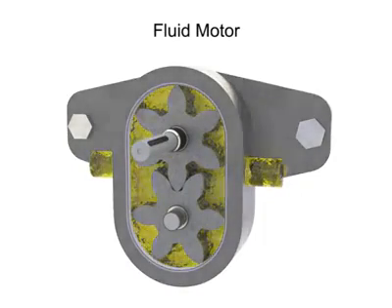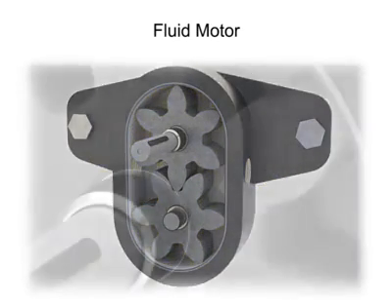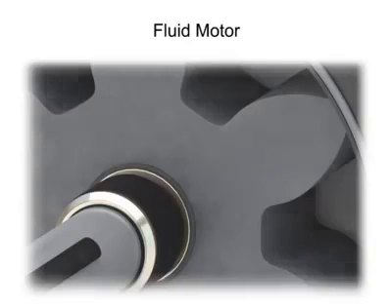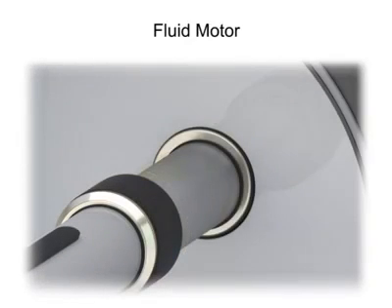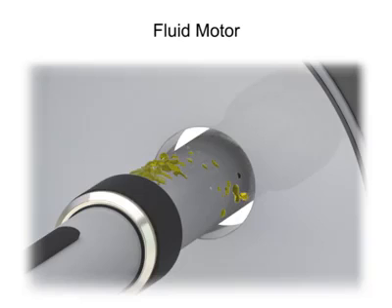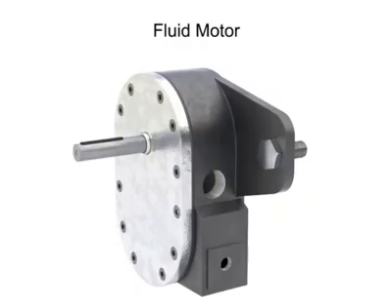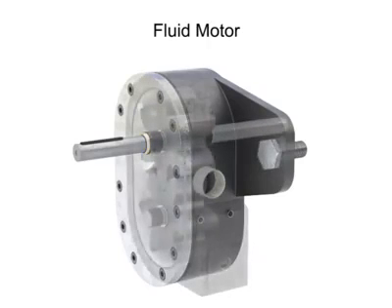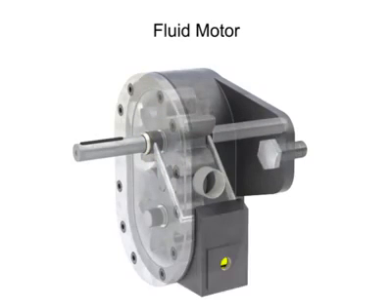In all hydraulic devices, a small part of the high-pressure oil will slip through clearances between the gear sides and the housing and will collect in the seal and bearing pockets. If not vented, these pockets would soon be exposed to the same high fluid pressure as the ports, which can then dislodge the shaft seal. To prevent this from happening, several motor construction methods are used. The first method creates an external case or housing drain. The seal and bearing cavities are internally joined and vented through a drain port.